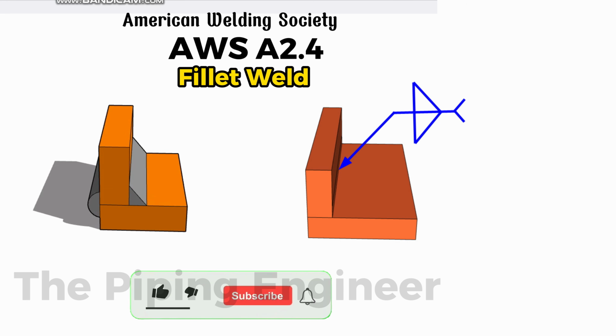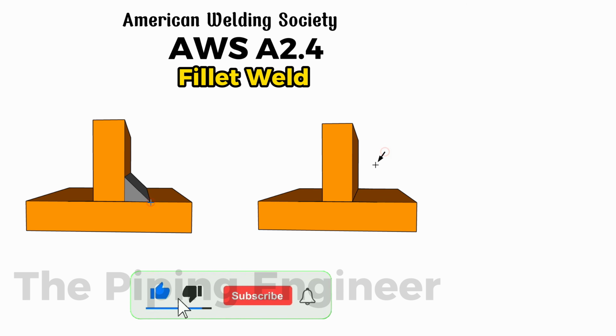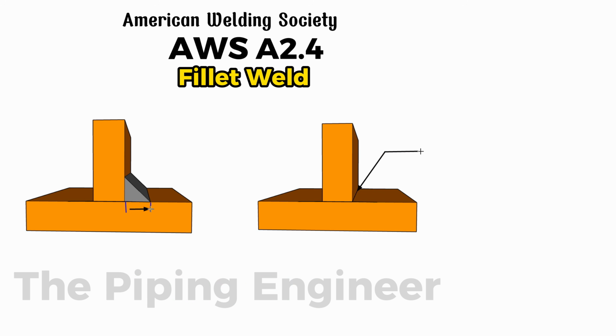If you look at most blueprints or weld symbols, you'll usually see a number sitting right before the fillet weld symbol. What that number's telling you is the leg size of the weld, basically, the length of one of the sides. It's super important for making sure the weld is the right size and actually holds up to the design specs.